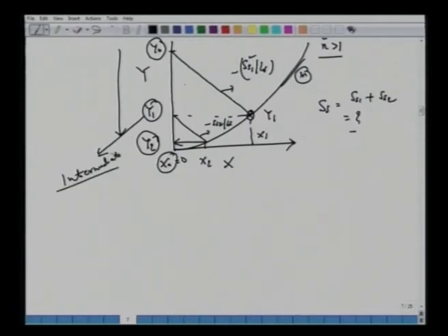If you fix any of these variables, suppose you fix Y1, you can go back to this, you can draw this line, then we can calculate from the slope how much is the amount of the solid required. Once we know Y1, we know Y2. Okay, from here again Y2 and X2, they are in equilibrium. The last stage, we fix this point, you connect this, you get SS2 here. Alright, so any of these three quantities, Y1, SS1 or SS2, if we know, we can complete this discussion here.